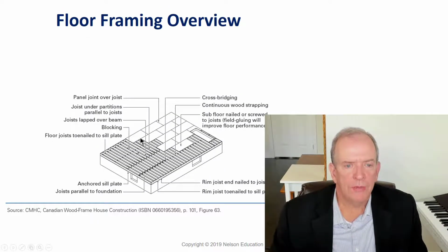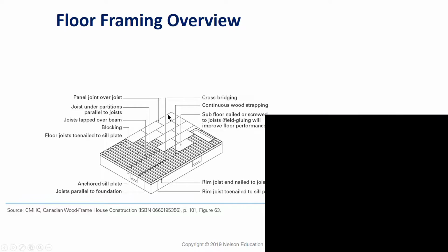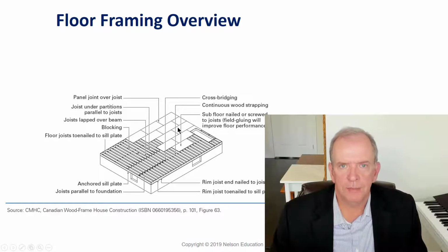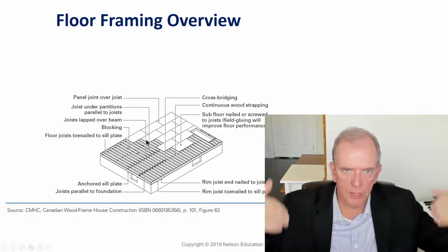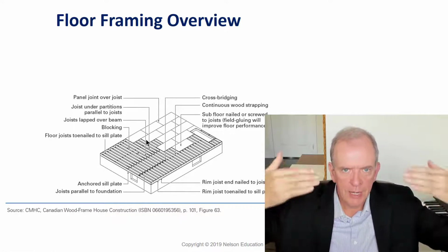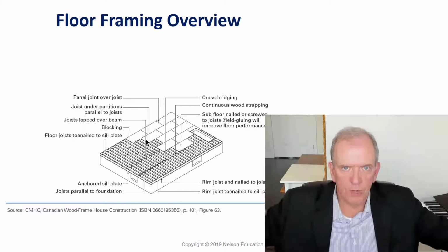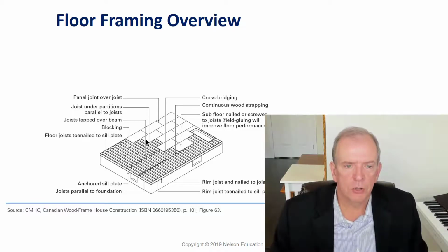And when we lay down the subfloor using dimensional lumber, we should stagger it. It doesn't matter, dimensional lumber, engineered lumber, we always stagger it. Same with drywall, we stagger it because if we have one straight joint going all the way along, it's not as strong as this is lapping over it. And when we screw down or nail down the subfloor, it dramatically strengthens it where every second sheet bridges over.